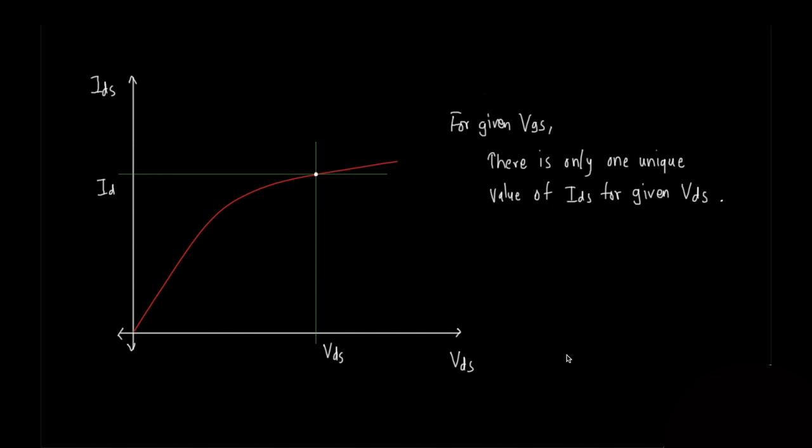This is similar to the case in the previous video where we calculated how much current IDS changes if we give a nudge to input VGS. The change in output voltage delta VDS can be evaluated as ID times the change in the resistance from the drain to source of the MOSFET. As IDS is constant, the only component that changes will be the change in Ron, that is the absolute resistance of the MOSFET as VGS changes. Gain will be the ratio of change in output voltage VDS to change in input voltage VGS.